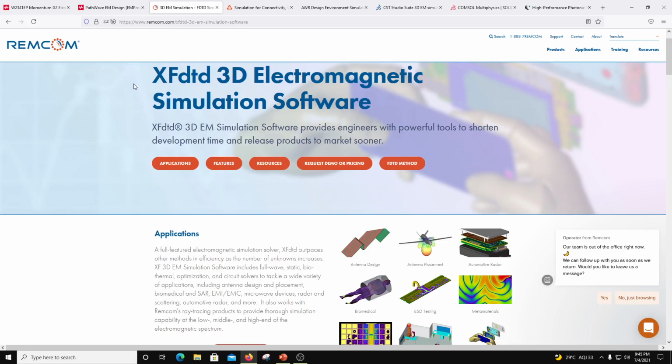Now in FDTD, the same box concept is there. You put an object inside a box, but then this box has certain properties, like it can be a perfectly matched layer, or PML, which basically absorbs all the radiation thrown at it, but not at all incidence angles. Perfectly matched layers are basically a numerical adjustment to collect all the fields without reflecting them back in. The reflection depends on the incidence angles.